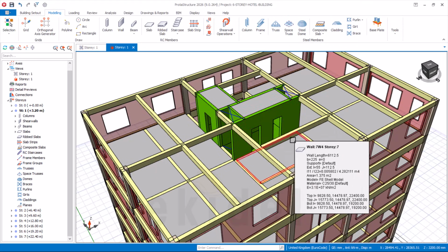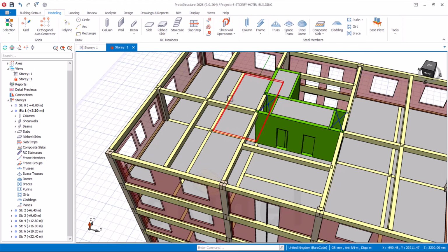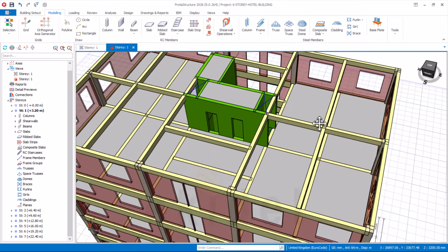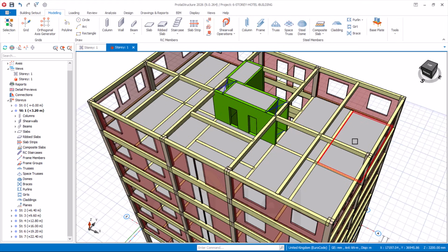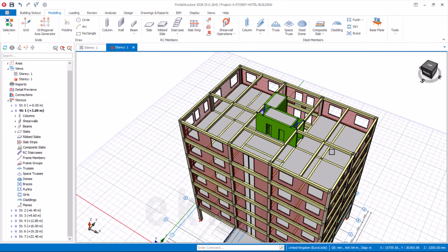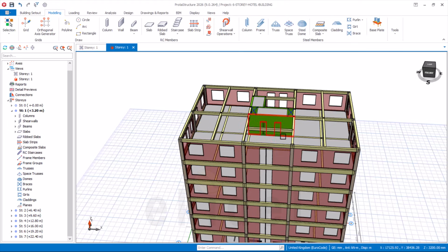Now you can see that we didn't add wall load on the intermediates. That's because we have already added the load on the slab, and these beams basically are not passing through where block walls are actually passing. So we didn't add that.